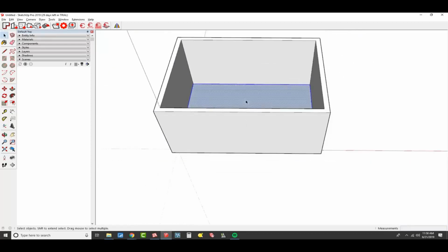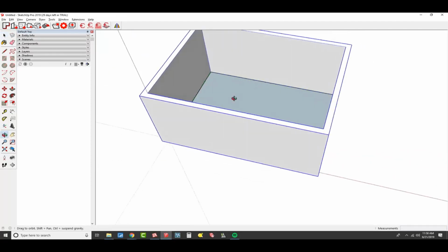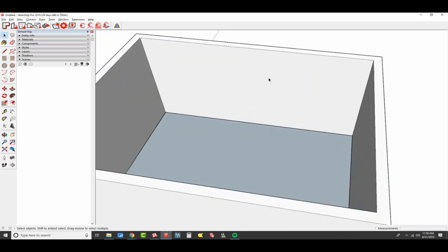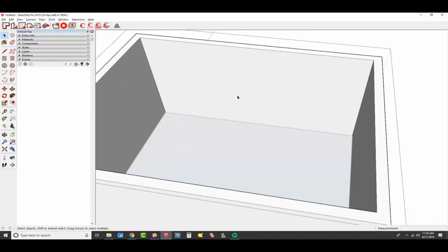Then I'm going to make this into a group. And then I'll draw a ceiling on here, just so we have it like that, and we'll make that into a group and hide it. Then I'm going to elevate this wall. I just want to throw some very simple shapes on here, like let's set our door at 8 feet tall, and I just cannot draw without being accurate.